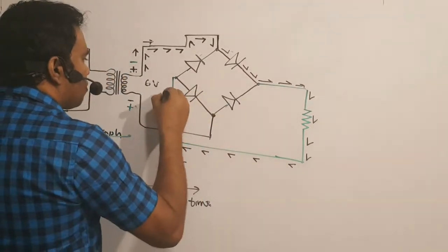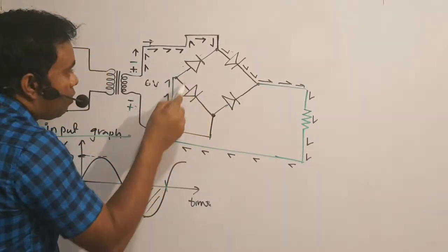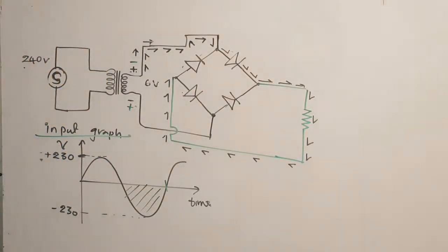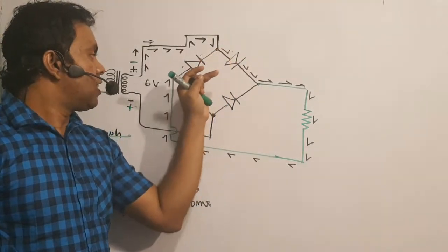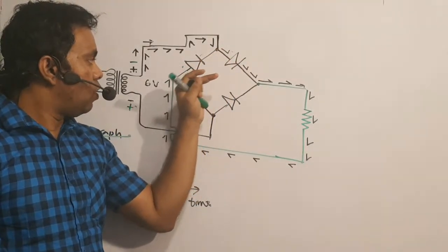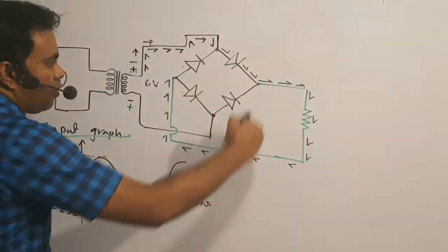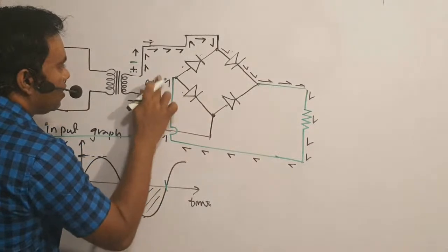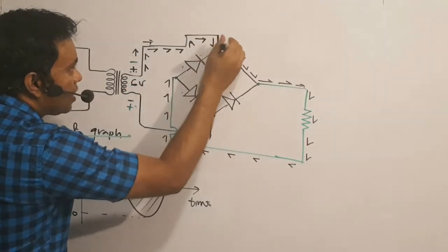Okay. The same problem again. Both are forward biased. Now, is it going through this first rectifier diode? No, it goes down because here is high potential. After going around, the voltage here has dropped below 6 volts, but here 6 volts already exists.